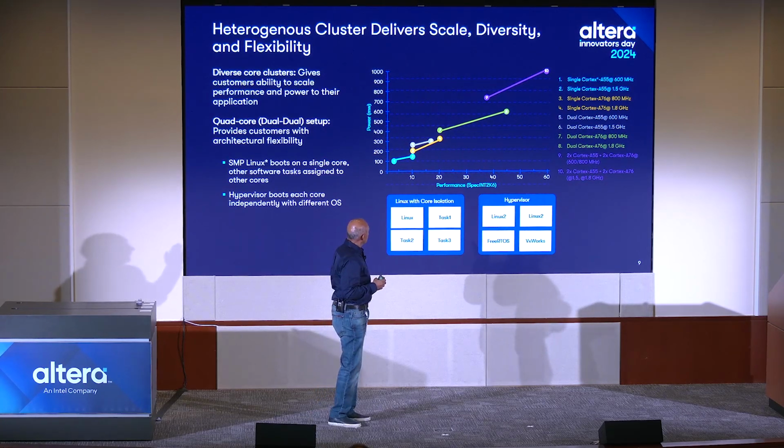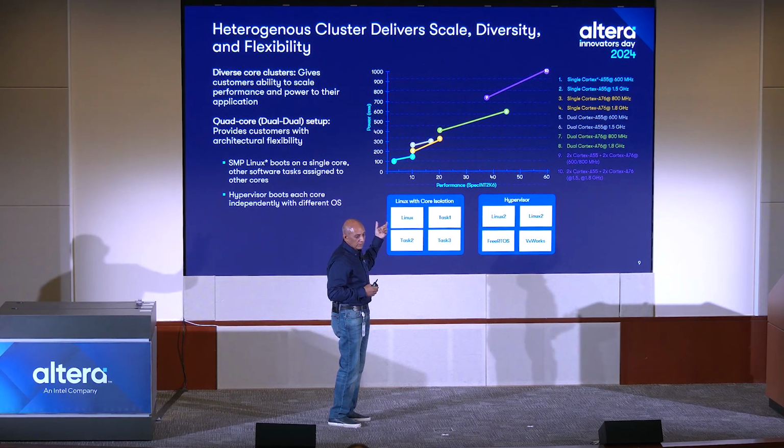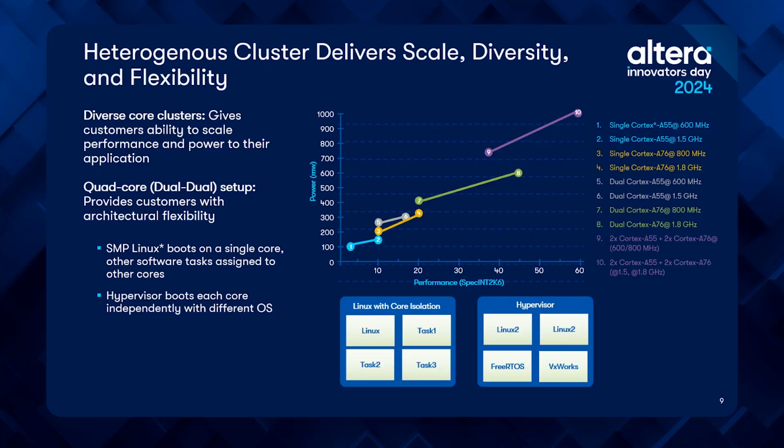So there's frequency scaling, and the blue line is really where you're looking for power optimization. My performance needs are low, so I could run an A55 and boot up an RTOS on it, or something for a safety-critical application. My performance needs may be different, so I could do that, or I could go to the top end, which is your number 10 there, which is when I need a lot of performance in my application, where I have algorithms that I'm running or something else, right?